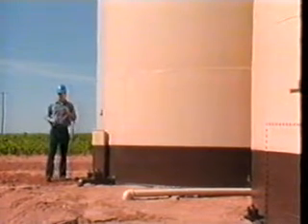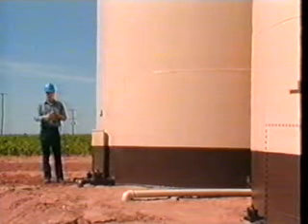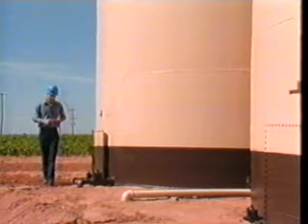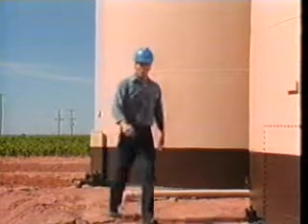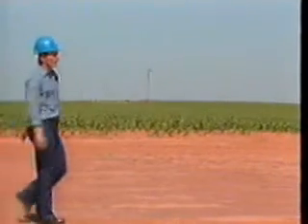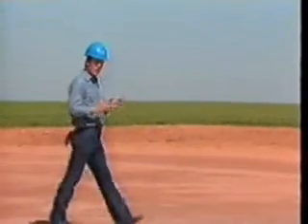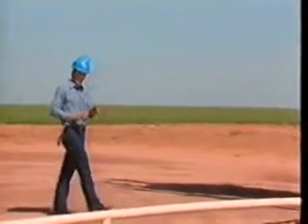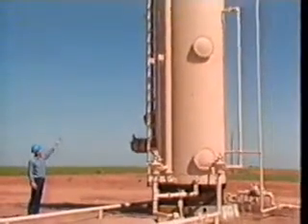Because we aren't just pumping oil out of these wells, but a mixture of well fluids made up of oil, gas, and water. Now, this mixture is so thoroughly blended that it can be pretty difficult to break into its three basic parts. Often this mixture, or emulsion as it's frequently called, must be specially treated before it will separate into its components. Much of this process is carried out in a heater treater.